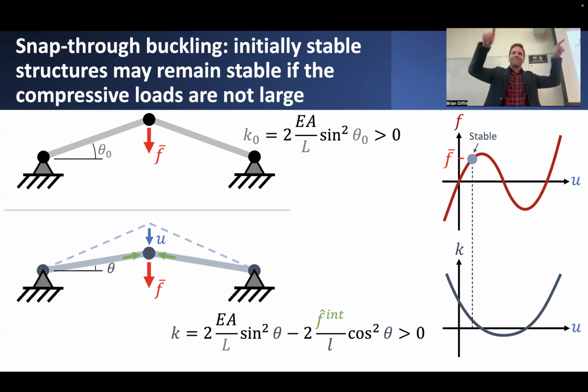Imagine what happens if you have this arch, and assuming that all the material behavior is elastic, suppose you took that external force and increased it, and the arch keeps compressing downward and downward. What happens as it continues to deflect downward? It'll approach more of a straight configuration, meaning that its apparent stiffness will be decreasing as its arched configuration goes down.